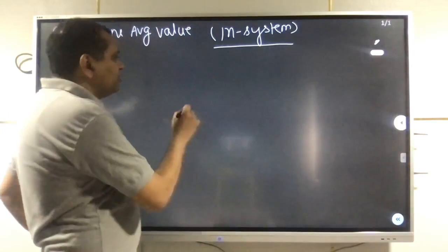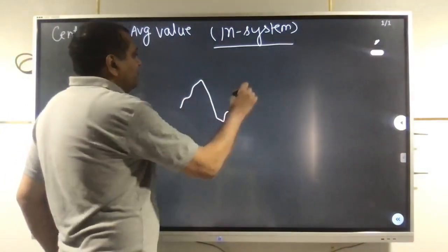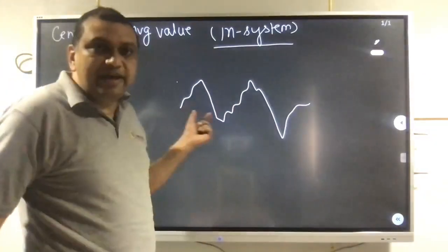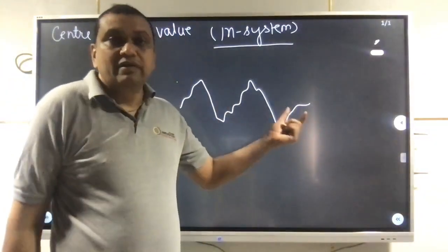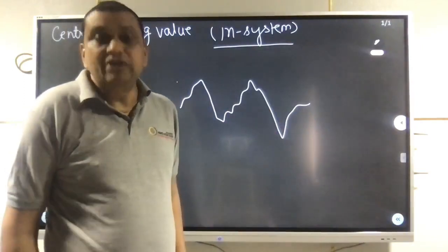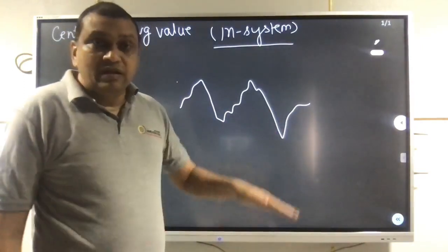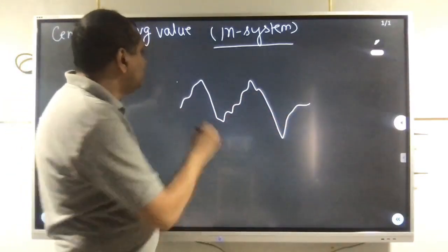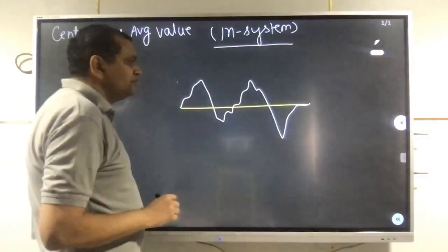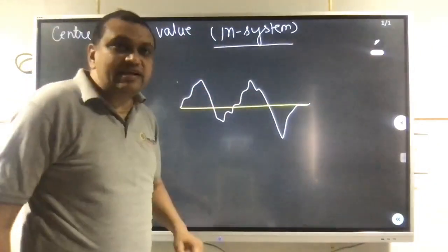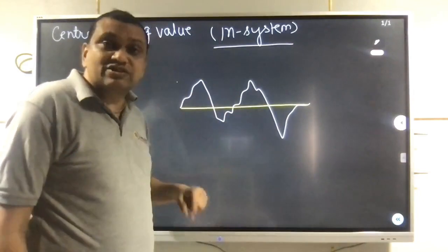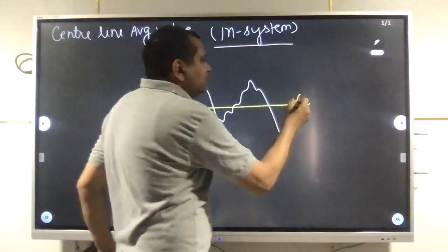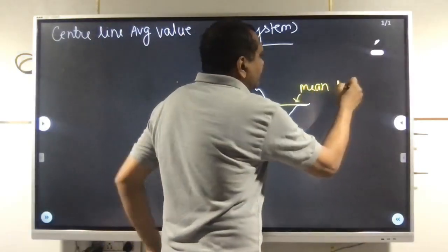So, after plotting the surface characteristic, by joining the first and the last point, you draw a reference line. Now, the reference line is shifted in the vertical and downward direction to the point that the area above the line and the area below the line is the same. And this line is called the mean line. So all the measurements are taken from this mean line.